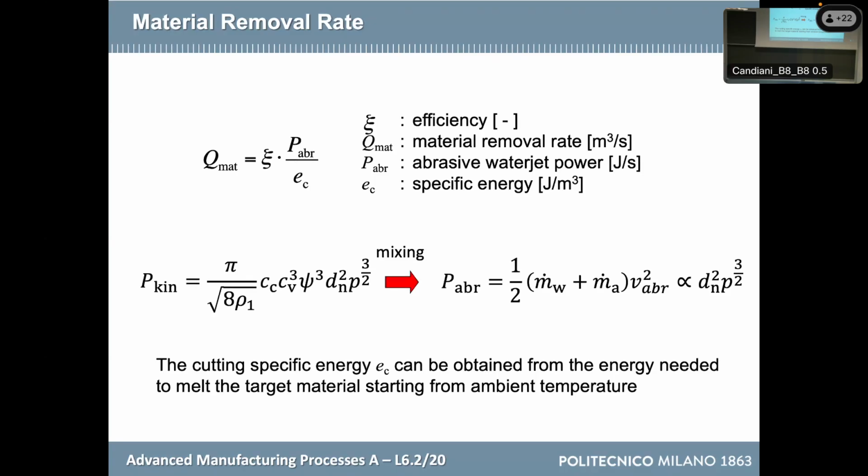If we do it, we understand how Kc for chip removal processes is really high with respect to other processes. Probably water jet is somewhere close to the chip removal processes, because at the end, also water jet is removing a chip. Instead, if we compare with forming, it is much lower. The energy that we have to put in for forming is closer to the minimum value required by the material to be deformed.